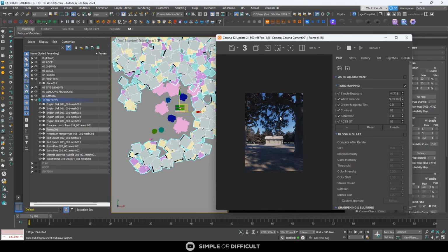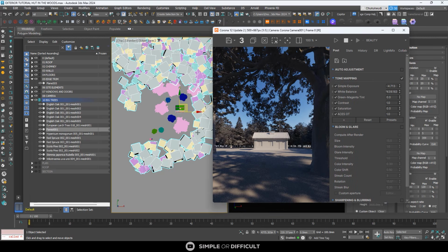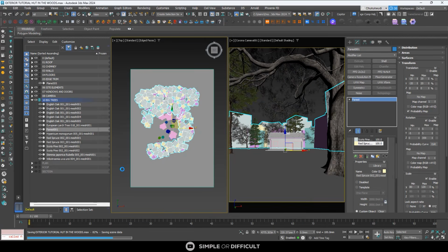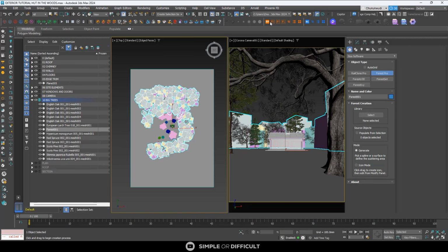Okay, so the next thing I want us to do right now is to go ahead and add the bushes. Okay, just like we added this one. So I'm going to stop this, Control S to save. We've done a lot. I wouldn't want to lose the things we have done. Okay, cool. So I'm going to create another forest pack. Okay, there's forest 1. I'm going to call this Big Tree Scatter.